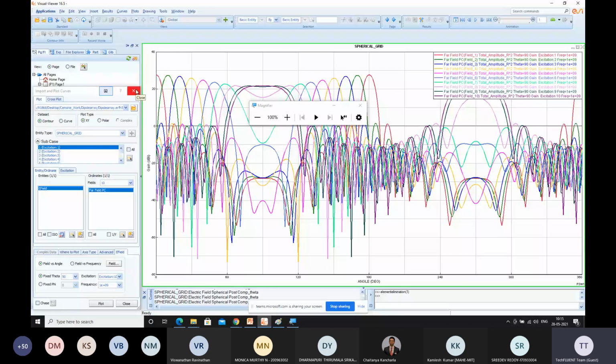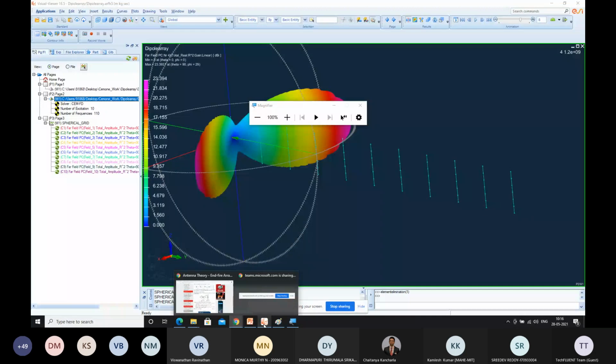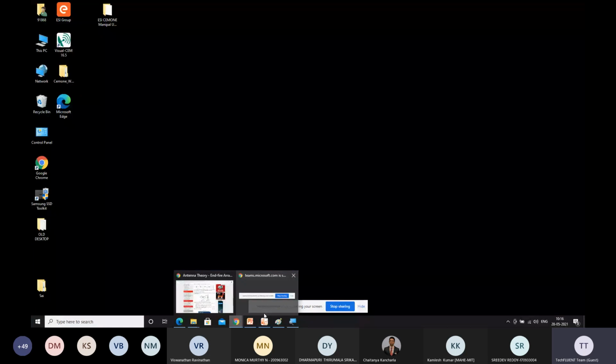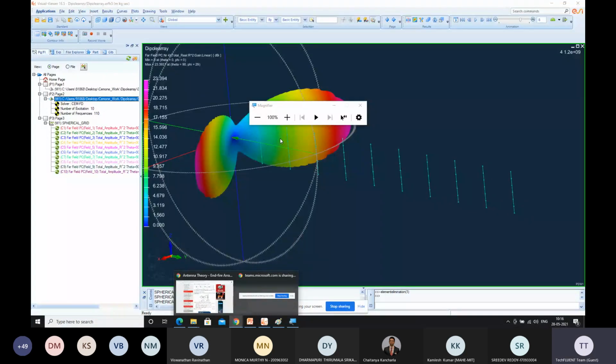So Rohit sir, one more question. Yes, sir. The feed element is a single point, correct? Which is providing for all the dipoles. And from a testing point of view, we have a single channel, correct? We have to connect. Yes, sir. Are we going to check the resultant gain or individual gains? Okay, you are asking whether we will be checking the resultant gain, sir. If you are going for dipole, especially a dipole antenna array, you have to go for the resultant gain basically instead of checking the individual gains.